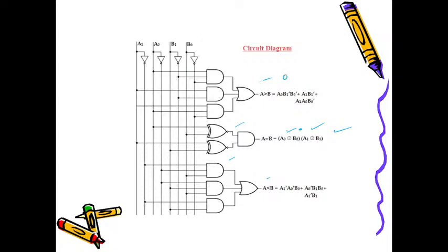So this is an OR condition. That is why I'm making use of an adder, plus. Did you get it? So you should make use of an OR gate here and an AND gate here. This is how you can simply denote your expression in terms of your logic diagram. So this is your 2-bit magnitude comparator logic diagram. Hope you would have understood.